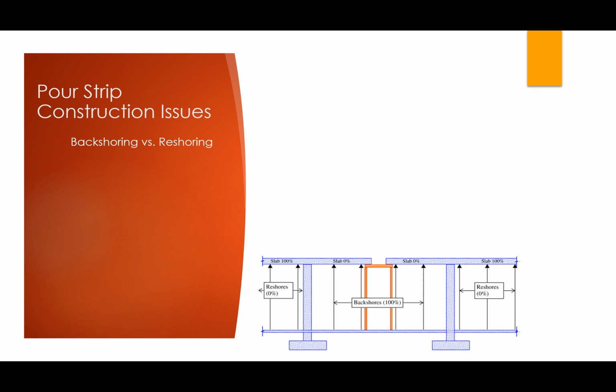So this is a critical difference, and I want you guys to really burn this into your mind here, the difference between a backshore and a reshore, because it's absolutely critical. And it's not something that engineers tend to be too familiar with, but we're going to see why this is very, very significant. So there we go, backshore versus reshore condition, right? Loaded versus unloaded condition. So now let's go ahead and pour level 3.